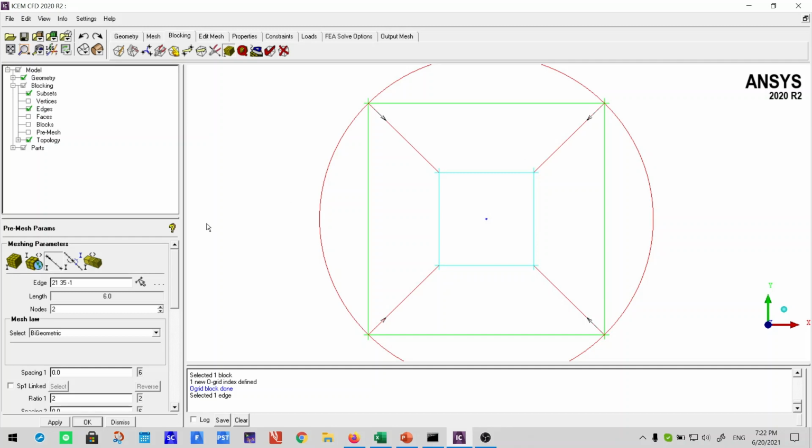So let's split under some specific number of divisions. Let's say I put a random number, 20. So these divisions are 20. This radial division will be 20, and all of them will be circular. This is the O-grid that I called O recently; the mesh will be like an O.